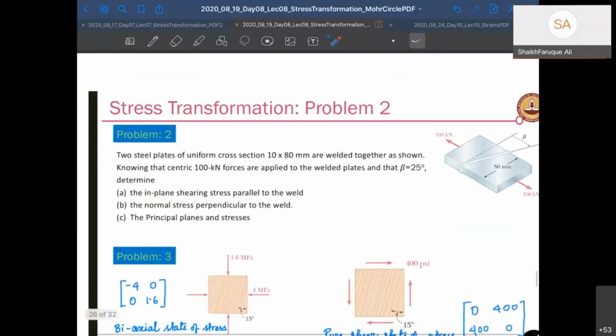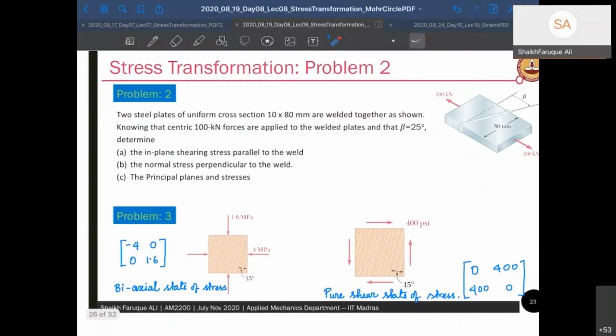Okay, so do these problems by yourself that are given here. I'll stop here. I have given how. So can you quickly tell what will be the diagram for this? Any one of them, quickly. So there is no shear stress, right? This element has no shear stress, and since it doesn't have any shear stress, these are the principal stresses themselves. So they will work like this point, and then the 0 degree line is the x-axis itself here.